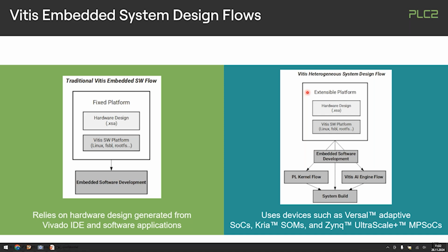Well, it still is a complete bitstream. It still is a complete design. So it's really functional, no problem there. But it's at least marked for extension. And this mark for extension then gets picked up by Vitis, and you have a software-defined flow. That software-defined flow would then be able to integrate additional hardware blocks by means that we will see in a second.